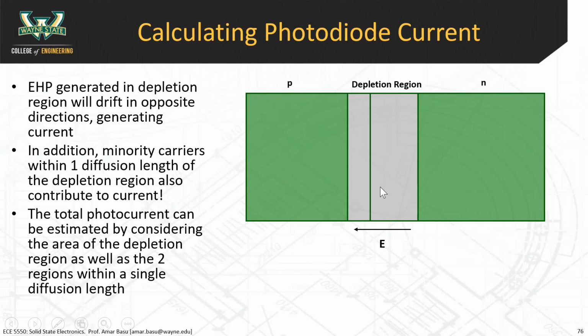Great, perfect. All right. So the key factor in photodiodes or solar cells is that you have this built-in electric field that happens on its own. That's one of the really amazing things about semiconductors. You have the P and N type material together, you generate an electric field in the depletion region, and it turns out that electric field is key for generating current in a solar cell. So let's look at what happens. We illuminate this thing with light. We're going to generate electron hole pairs everywhere, right? You agree with that? But it's the electron hole pairs that occur near the depletion region that actually matter.